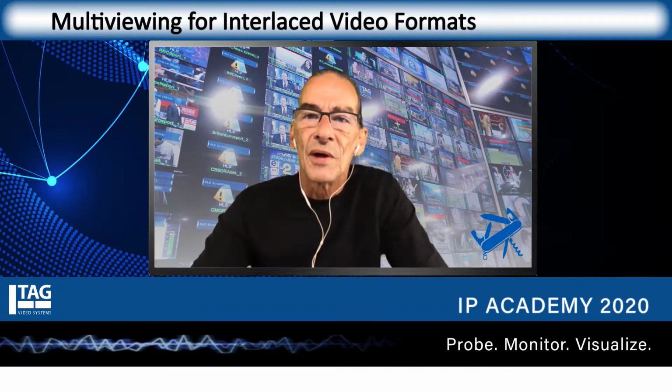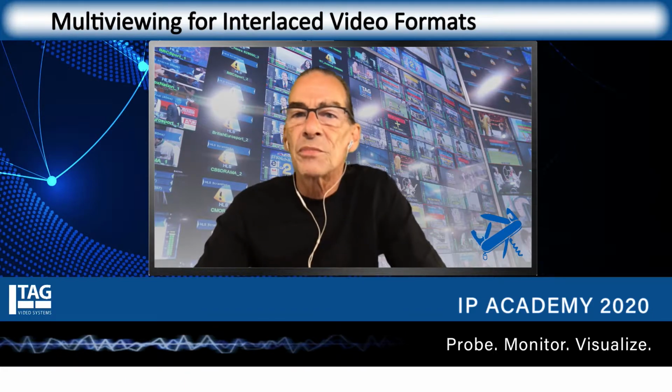The problem comes down to bandwidth in broadcasting, because there's limited amounts of bandwidth available in broadcasting channels. The technology of the day limited that, and in fact we don't want to use up huge amounts of spectrum broadcasting pictures. So an ingenious technique was developed to essentially provide data compression of the video signal. It took advantage of this artifact of the human visual system along with one other artifact. And that artifact is that when things are in motion, you can't perceive detail in the motion as much or as readily as you can in a still image.